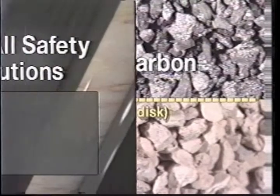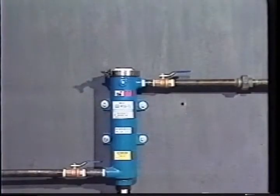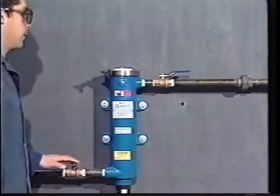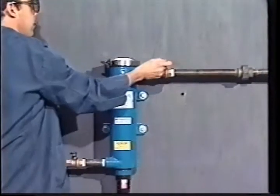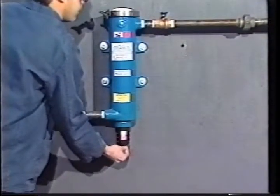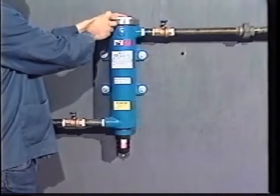the entire system. When changing the filter elements, all pertinent safety precautions regarding pneumatic equipment must be followed. Filenco has designed our equipment to permit desiccant change by any competent shop person. No tools are needed. First, the dryer filter should be isolated by shut-off valves upstream or downstream, or by shutting down and locking out the compressor on smaller systems, so the unit will not be opened under pressure. Residual pressure in the unit is bled through the discharge drain.